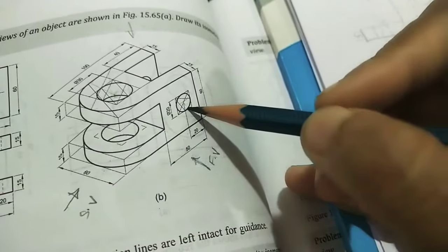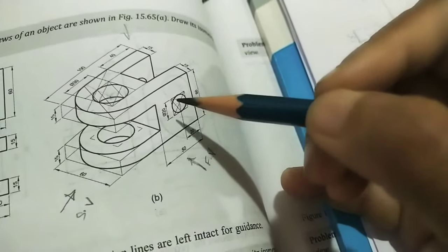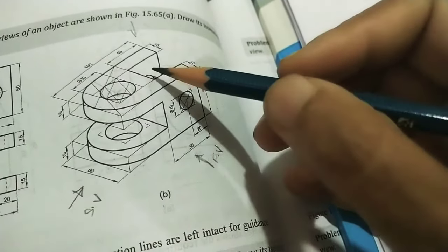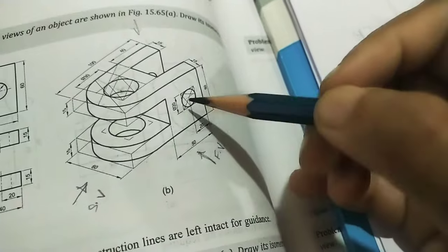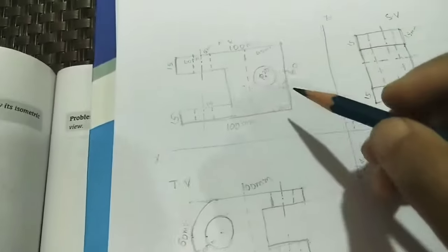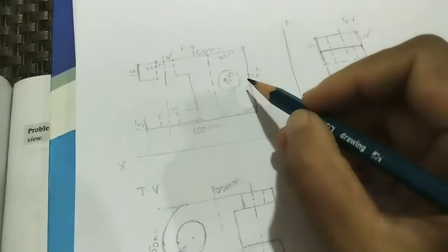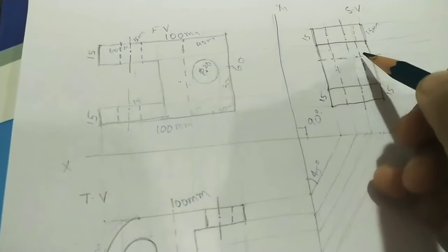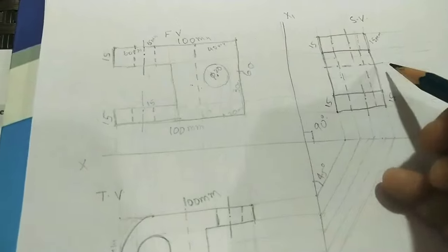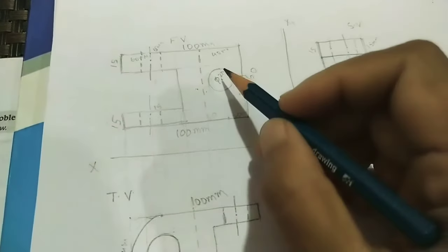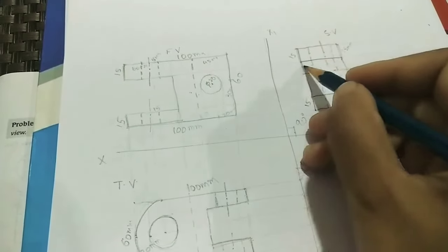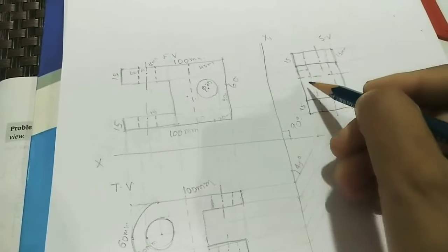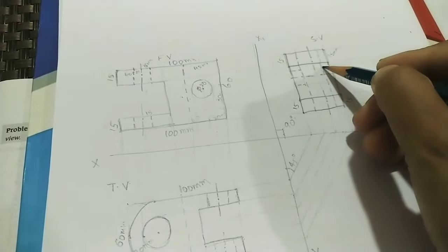After getting this thickness from the side view, we have to do the circular holes also. From the side we can't see these circular holes. So wherever these circular holes are, we have to take the dotted line. From the front view, we took the center of this axis projectile lines. Let us do the center line here, two big lines with a dot. Already I did here, two big lines with a dot. Center line, axis line it is. So wherever projectile lines are coming, we have to take the dotted. Here and here, here and here.